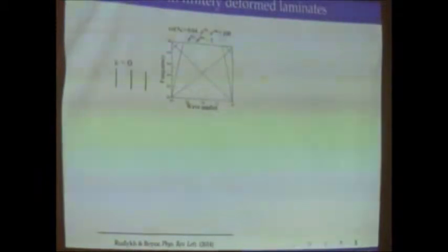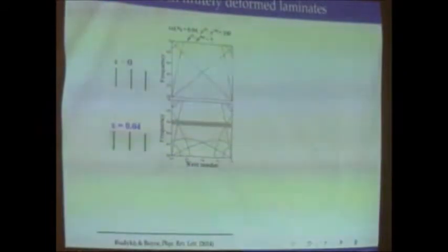So this is a dispersion curve, and waves go in the direction of layers. A typical dispersion curve with then deformed laminates. Now I start deforming these materials, and what I want to do here is compress the laminates. We have a soft matrix and stiff layers, and when we compress in the direction of layers, these stiff layers will buckle in some type of wavy pattern, and then that affects the wave propagation in the same direction.